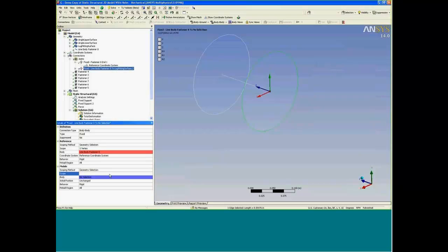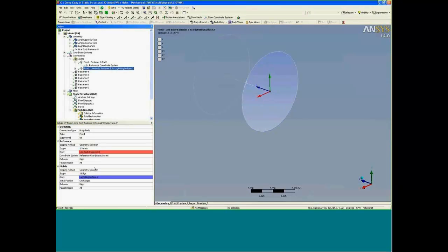And when it does that, it creates a local coordinate system. It creates that connection between the two. That kind of confirms connecting the beam. You can have a rigid or flexible behavior with a rigid connection to that edge. It somewhat rigidizes that hole. You can also create a flexible connection there as deformable. That may be more of what you want to let this hole flex under load.